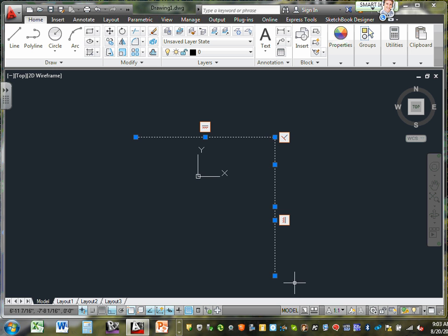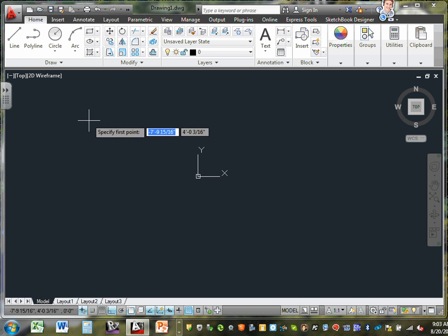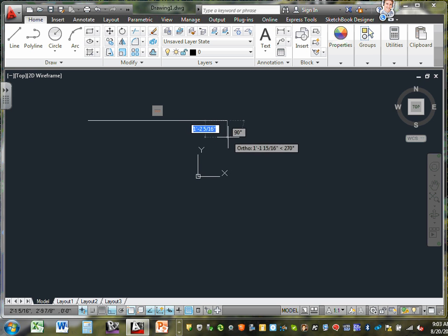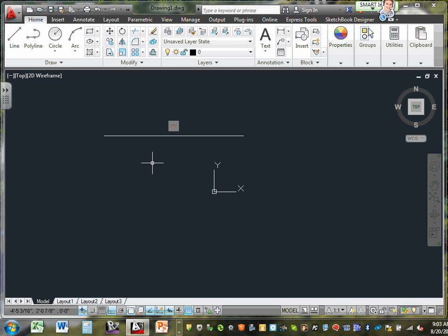One more time. Let's go. Create a line. Click on a line. Click here. Type 10. Can you guys type 10? Put the symbol for feet and hit enter. You got yourself a 10-foot line. Right now, are you guys still holding the line? If you want to finish the function of a line, hit skip. Can you see where it says skip? Hit skip. Now we have a 10-foot line.